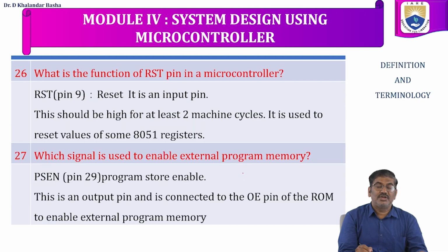What is the function of the reset pin in a microcontroller? Reset, which exists as pin number 9, is an input reset signal to the microcontroller. This should be high for at least 2 machine cycles. It is used to reset the values of some 8051 registers.